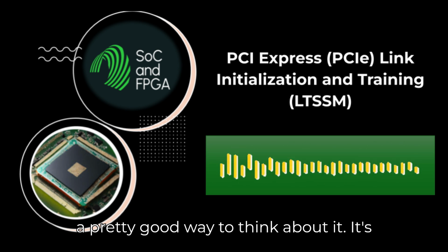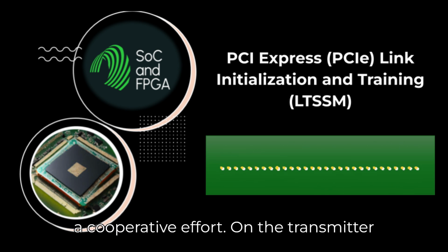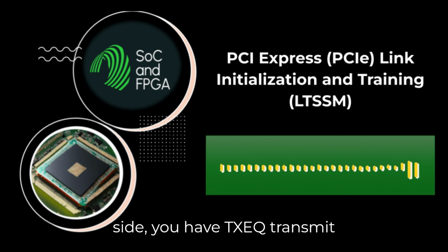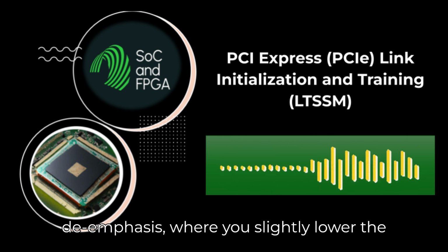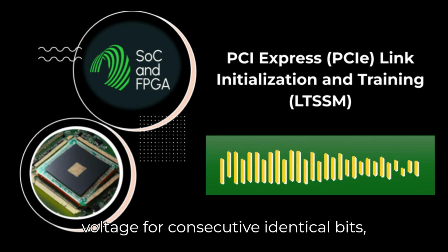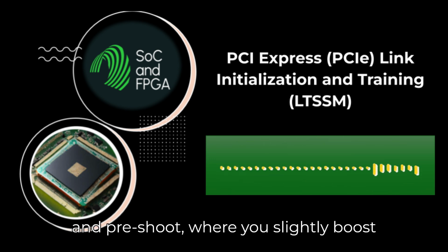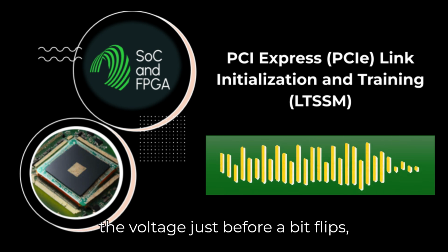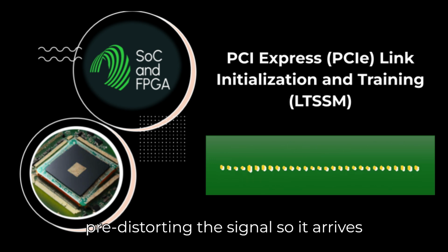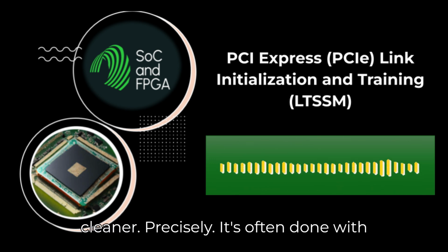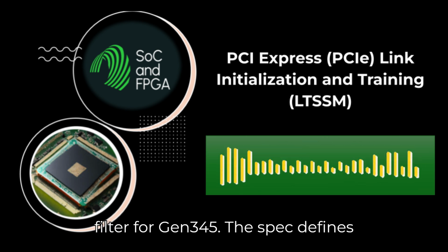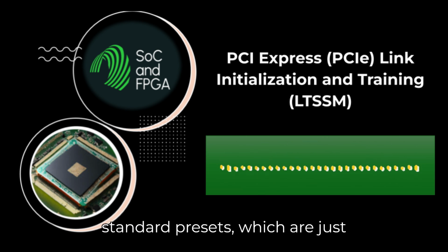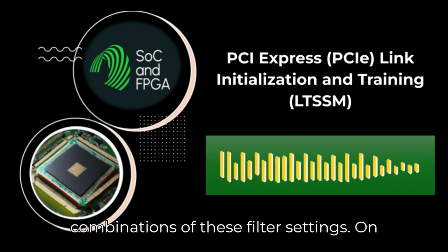So it's like noise cancellation and signal boosting specifically for high-speed data. That's a pretty good way to think about it. It's a cooperative effort. On the transmitter side, you have TxEQ, transmit equalization. This involves things like de-emphasis, where you slightly lower the voltage for consecutive identical bits, and pre-shoot, where you slightly boost the voltage just before a bit flips. Pre-distorting the signal so it arrives cleaner. Precisely. It's often done with a digital filter, like a 3-tap FIR filter for Gen 3. The spec defines standard presets, which are just combinations of these filter settings.